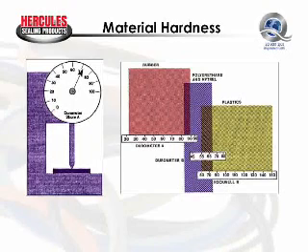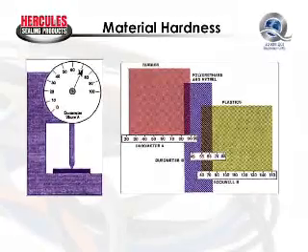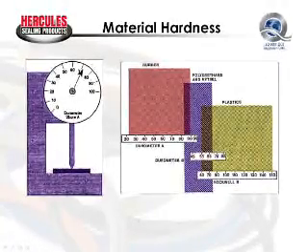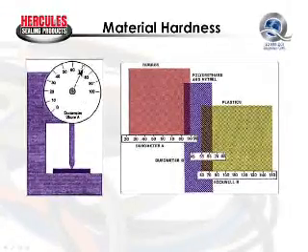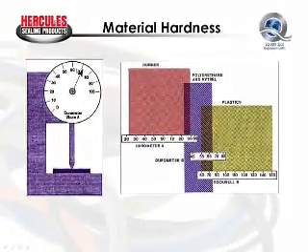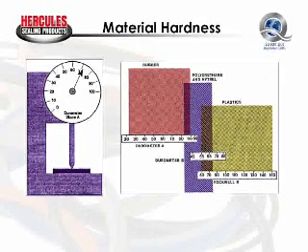When seal manufacturers are making seals, they do not measure the hardness of the individual seals because the shape of the seal will affect the material's hardness. But rather what they do is manufacture a test plug, they cure it, and then they measure the hardness of that test plug to verify its hardness reading. And like I said, there could be a plus or minus 5 on this scale. For our purposes, for your purposes, you can measure an O-ring or you can measure a U-seal and get pretty darn close to what the proper hardness is supposed to be.